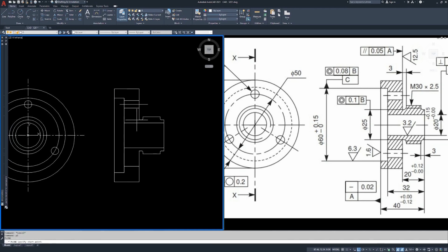I'm going to draw another polyline. I'm going to hit the midpoint there, grab the grip. I'm going to use the match properties, which is MA, right click. I'm going to match the properties of our center line over here to this center line and this center line.